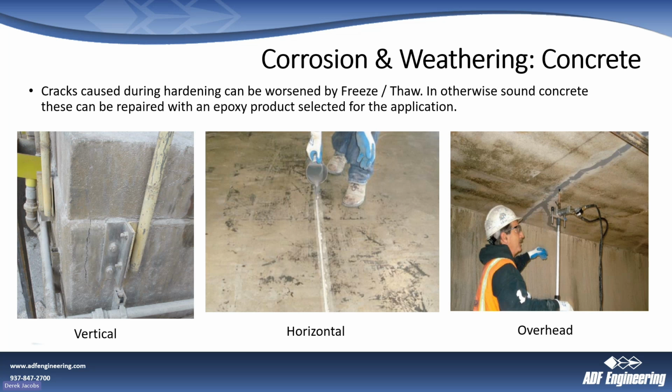Also, concrete will naturally crack during the hardening process if there isn't a sufficient amount of reinforcement included to resist that internal tensile force. It's normal, somewhat unavoidable, but also can be limited to a negligible amount with the proper reinforcing. But sometimes, if that's not the case, or even with those small cracks, water can get in. You have your freeze thaw issues, or maybe the cracks are big enough to where it's maybe a design issue and it wasn't reinforced enough. So typically, cracks like this will be repaired with an epoxy product.